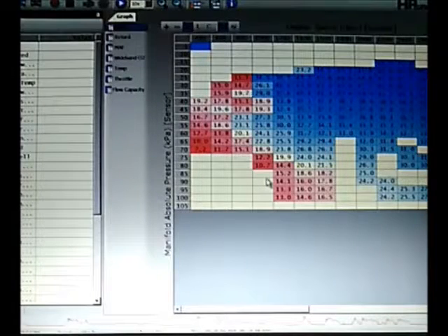Because especially with open loop, the numbers really shouldn't change over time. Like I said, they don't drift with a VE tune unless you make physical changes to your car. But having said that, you still want to make sure that you get it really dialed in well, and that does take considerable time, because these numbers are very sensitive.